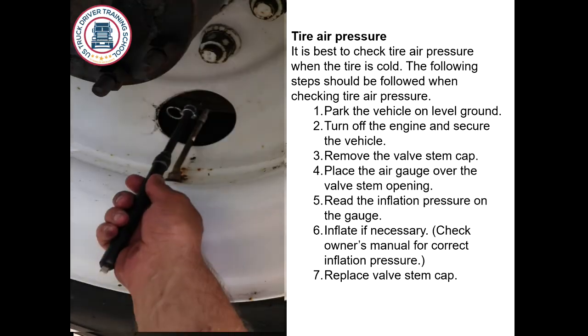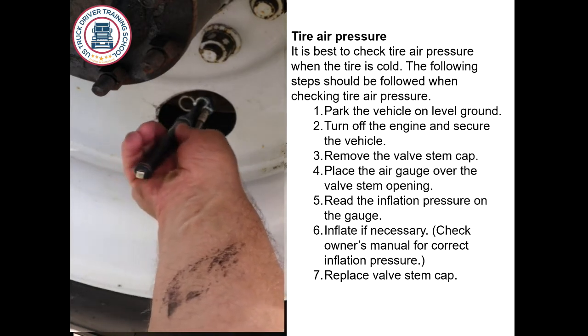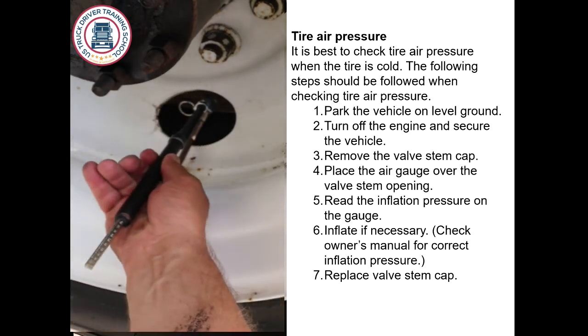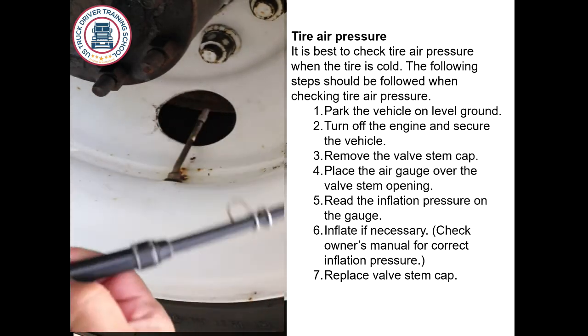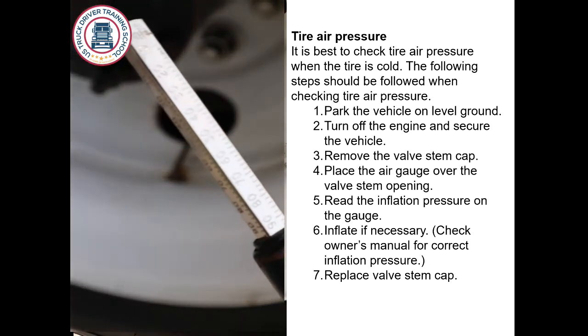Remove the valve stem cap, place the air gauge over the valve stem opening, read the inflation pressure on the gauge. Inflate if necessary. Check your owner's manual for correct inflation pressure, then replace the valve stem cap.